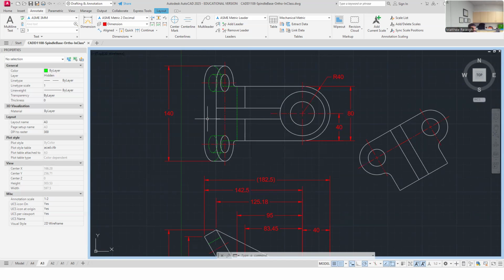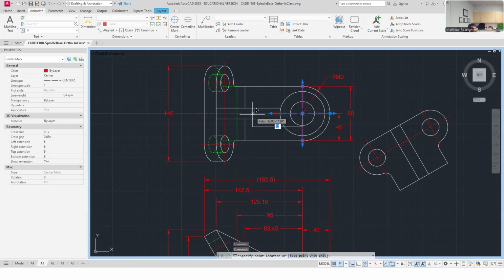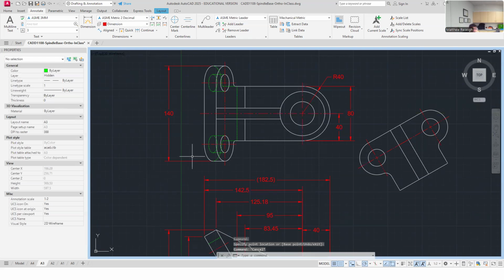But when I came to my top view and I thought if I'm going to dimension anything, I'm going to pull this control further over. I'm going to pull this control through the part. And I'm going to show that there's this horizontal alignment from this control through this part. This is now symmetrical over a center line. And I feel like if I'm going to dimension anything here, I'm going to dimension it from this center line here and not necessarily from this outermost radius on the back or front side. So all I've had to do is pull this controlled plane through my part.